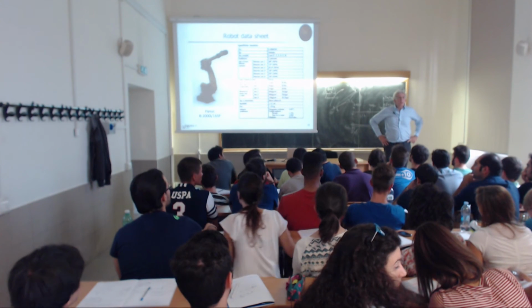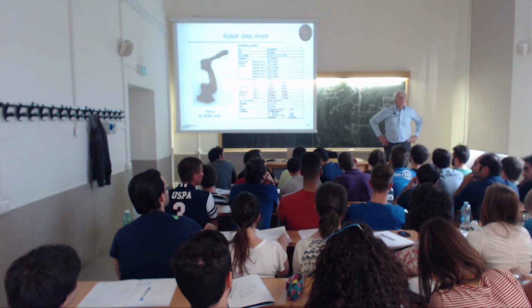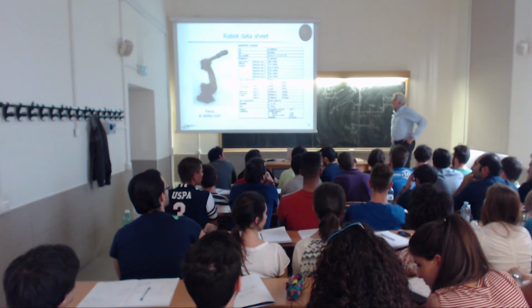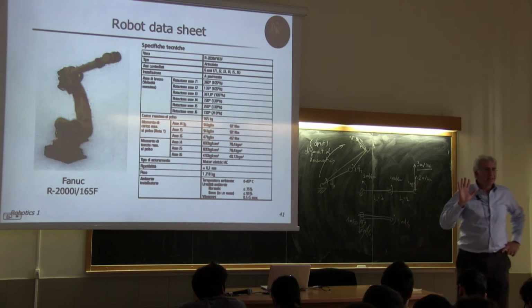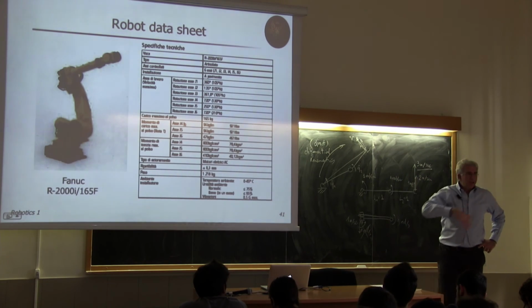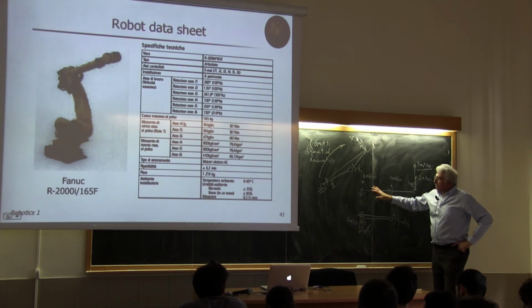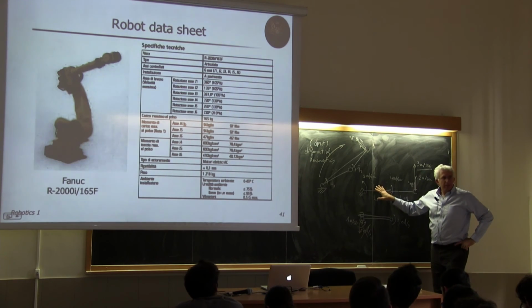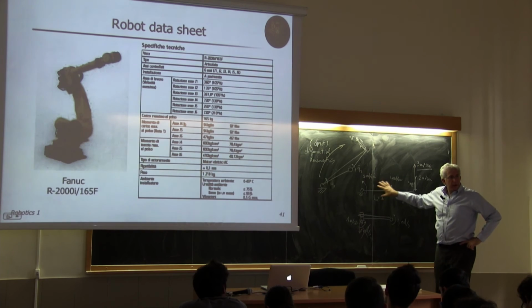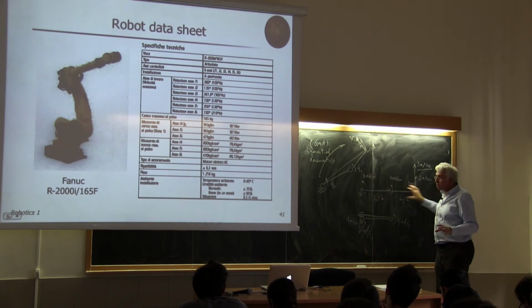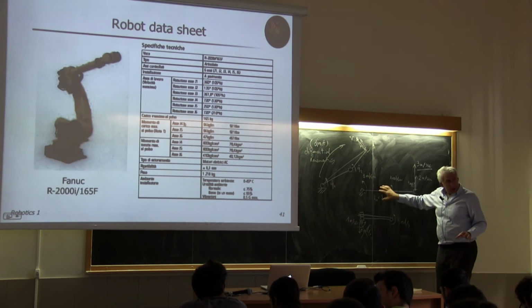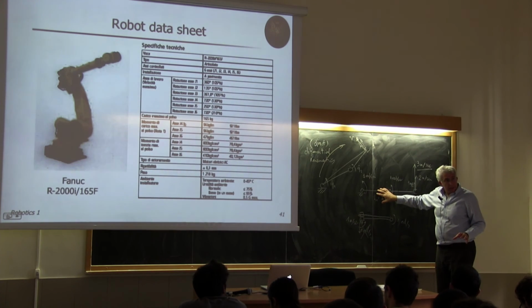The number of joints, of frames. So I've not yet talked about frames, but since probably you're looking ahead, the number of joints will give us the number of frames that we have to define for the structure, one for each link. Remember, the frames by which we characterize the position and orientation of each body of the structure are associated to the links.